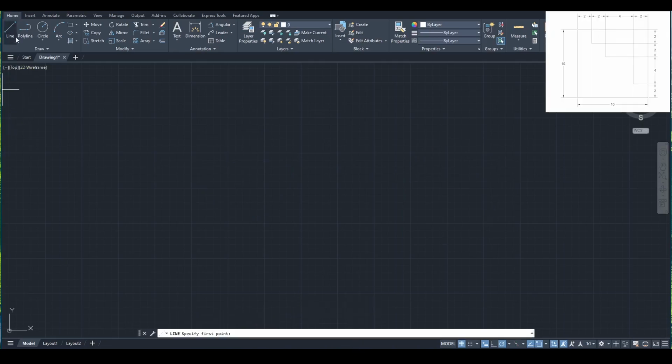So right now for the second example, I'm gonna choose the line command, or I press escape and then I'm gonna type LI for line and it just brings it up. I click on it and I choose it, and then I click somewhere on the screen which starts the line for me, and I'm gonna go 10 units towards the right direction for the second example. I'm gonna go 2 units up.